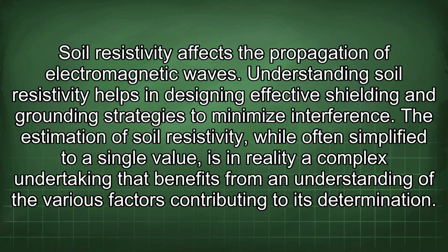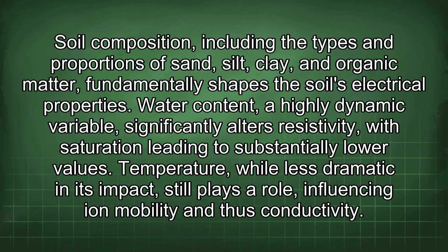The estimation of soil resistivity, while often simplified to a single value, is in reality a complex undertaking that benefits from an understanding of the various factors contributing to its determination. Soil composition, including the types and proportions of sand, silt, clay, and organic matter, fundamentally shapes the soil's electrical properties. Water content, a highly dynamic variable, significantly alters resistivity, with saturation leading to substantially lower values.